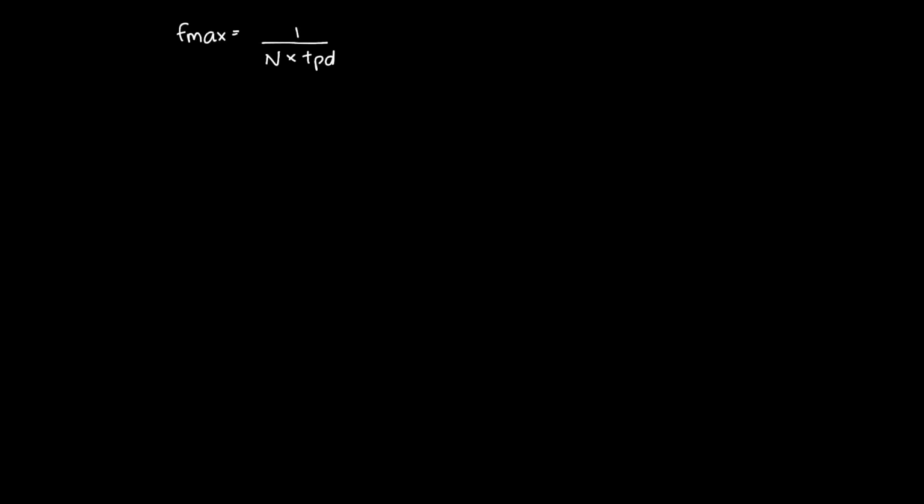So it's not 4 or 16 or 32 or what have you. I would only asynchronously reset when I have a non-natural mod number, such as 9, which is the example that we did. But that is not the case here. I do not have these glitches. My timing diagram, in fact, is going to look great.